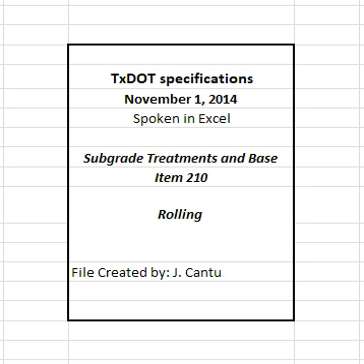2.4.3 Heavy pneumatic tire. Furnish a unit with at least 4 pneumatic tired wheels mounted on axles carrying no more than 2 wheels, with wheels arranged to carry approximately equal loads on uneven surfaces, with a width between 8 and 10 feet that can turn 180 degrees in the crown width. Capable of providing a total uniform load of at least 25 tons. With tires capable of maintaining a maximum ground contact pressure of 150 psi, and with liquid-filled tires inflated to such a level that liquid will flow from the valve stem when the stem is in the uppermost position.